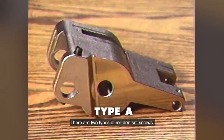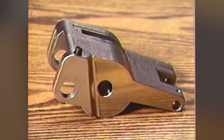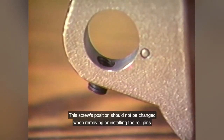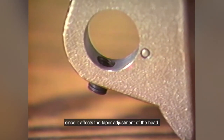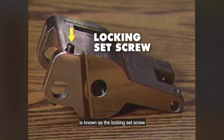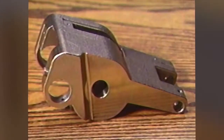There are two types of roll arm set screws, Type A and Type B. For Type A, one set screw is located on the inside portion of the roll arm assembly and is known as the taper adjusting set screw. This screw's position should not be changed when removing or installing the roll pins, since it affects the taper adjustment of the head. The second screw, located on the outside portion of the roll arm assembly, is known as the locking set screw and should be used when removing or installing roll pins.